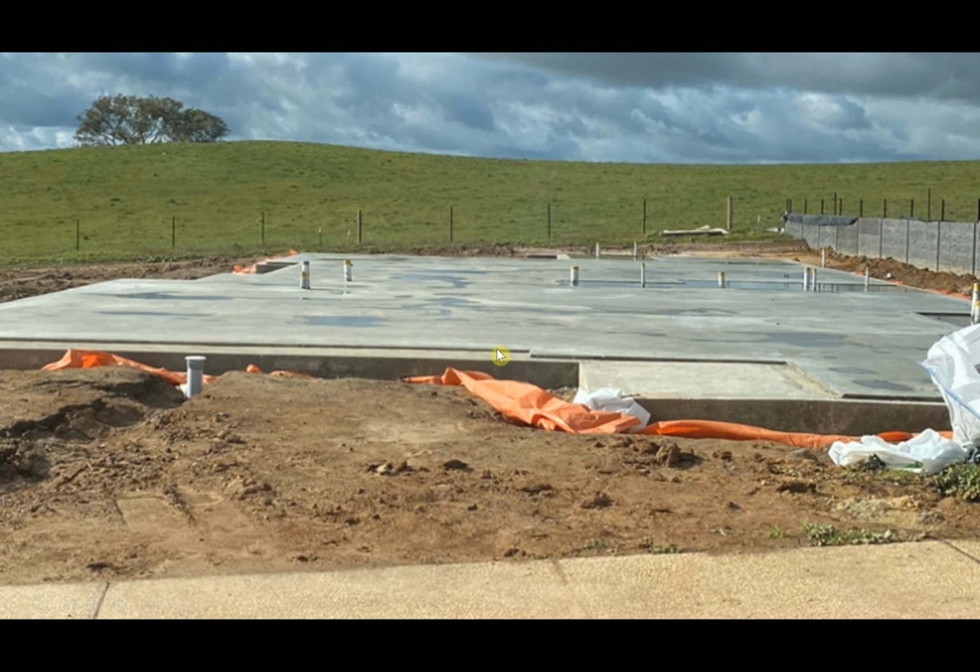So this is the finished slab. They've come in, they've poured the concrete over the top of all of this steel here, and this is how it looks. So we have our pipework sitting up through. We have these things here, which is a set down. So usually what happens is we set down our garage, our wet areas, and our alfrescos in the porch by 50 millimeters. Okay, this is to stop any water from pooling or running into the house. Obviously our wet areas are more prone to have water in them. So we set them down so if it fills up with water, it's not going to spread to the rest of the house.